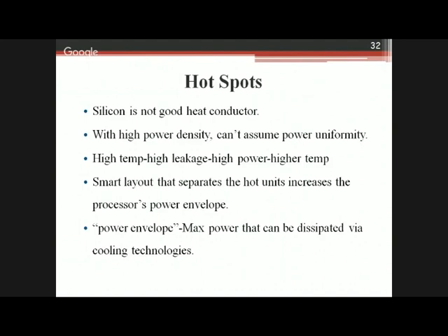So when those components are placed nearer to each other, a lot of power is going to be consumed at those particular points. Due to which a large power consumption happens there. Also, there is a high temperature at that point, which leads to high leakage, and that high leakage leads to high power again, which again leads to high temperature. So this forms a loop that continues again and again, and that is going to damage our chip or circuit. It might be the failure of our entire application.